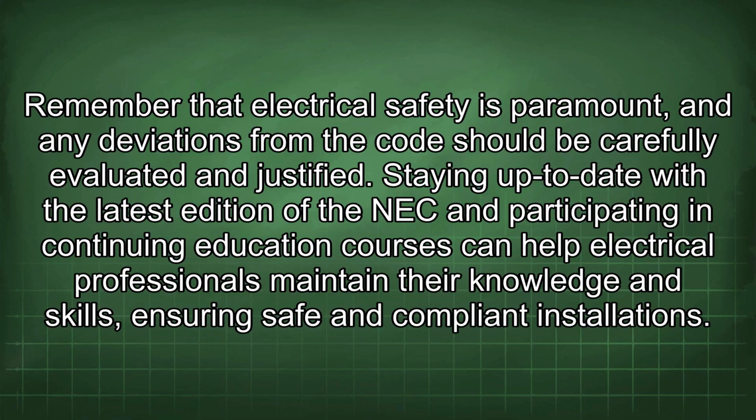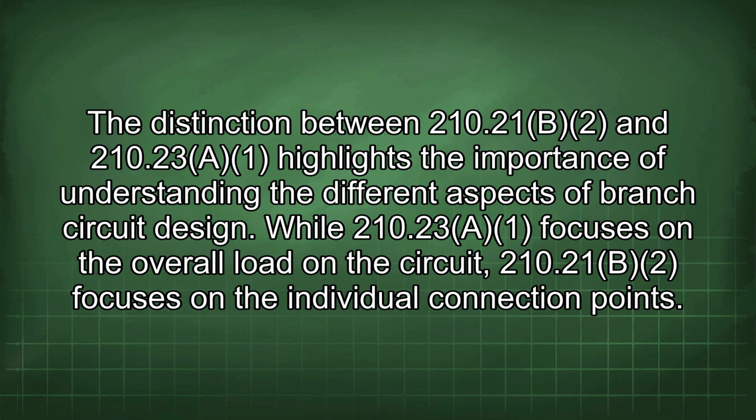Staying up to date with the latest edition of the NEC and participating in continuing education courses can help electrical professionals maintain their knowledge and skills, ensuring safe and compliant installations. The distinction between 210.21(B)(2) and 210.23(A) highlights the importance of understanding the different aspects of branch circuit design. While 210.23(A) focuses on the overall load on the circuit, 210.21(B)(2) focuses on the individual connection points.